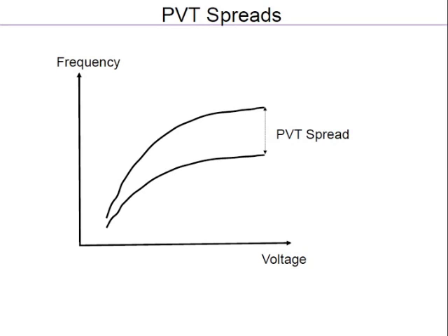So there are two concepts here. One is dynamic voltage scaling, where if you are running at a lower frequency, you adjust the voltage to be lower, just enough to run it at that frequency. So if I know I'm going to run it at this frequency, use this voltage. In addition, you also have to put a margin, because different chips from the same class might have different F2V characteristics. We can call this the F2V characteristic. It could be a little different, so you have to put in a margin for that, so that no matter what chip from that class is being used at that frequency and for that voltage, it will work.